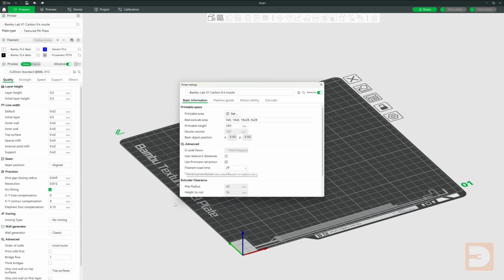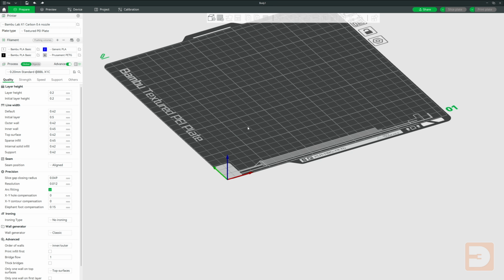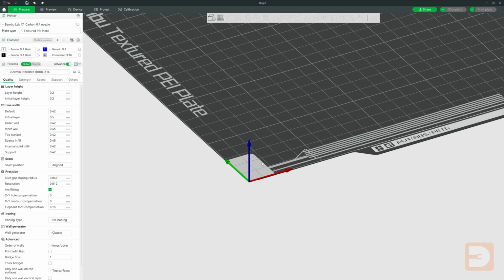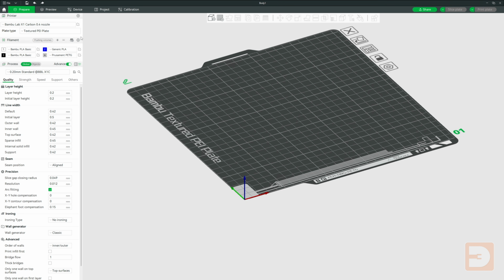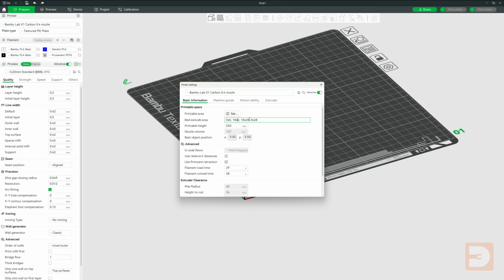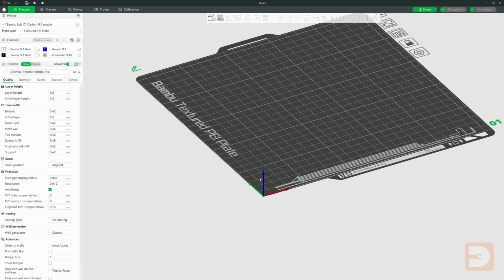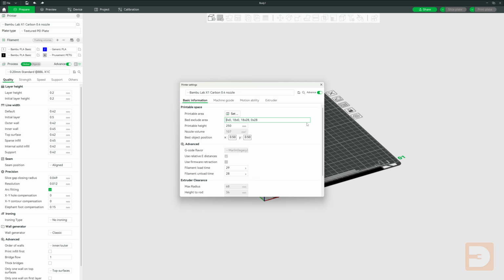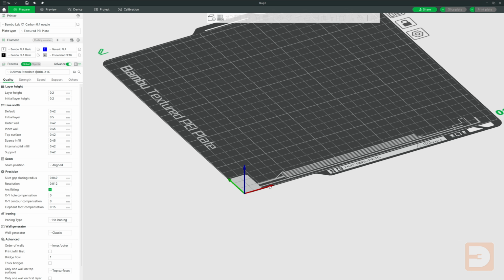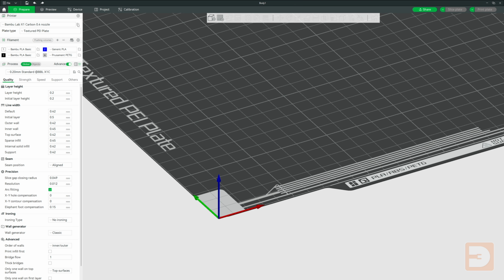As I have a Bambu Labs X1C selected, by default the area down here is excluded as this is where the printer goes to cut the filament when doing a filament change, and if you were printing in this area it could result in stringing or damage of your print. If you needed to print with absolute maximum volume on an X1C, you could just come here, delete the coordinates here, and then you'd be able to add models to this area without warnings. But now I'll just click the orange arrow here, that will reset its default, and you can see that it has added the exclusion area back onto the print plate.